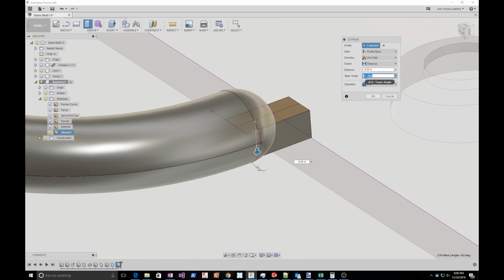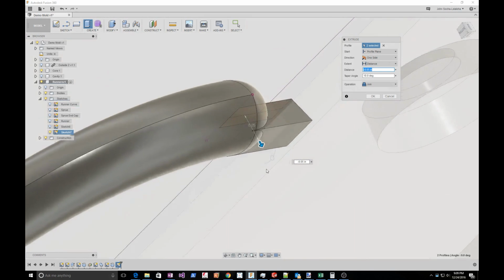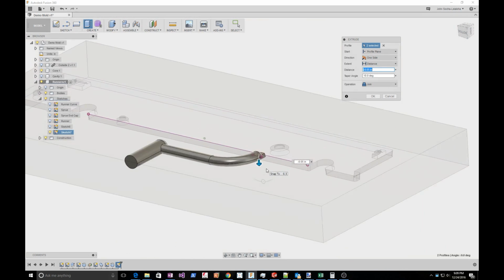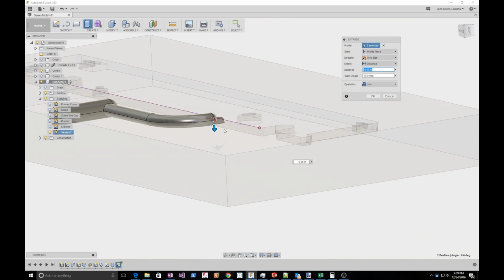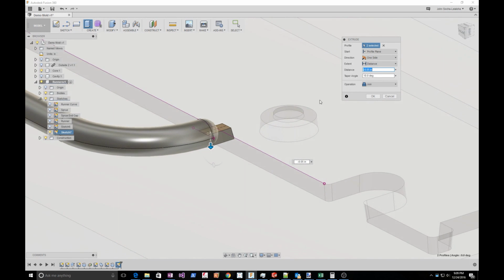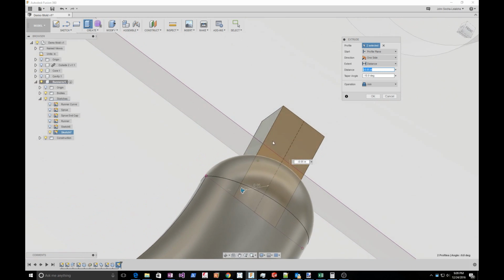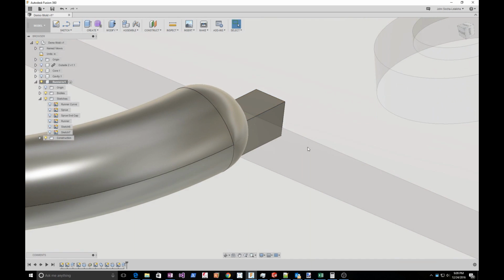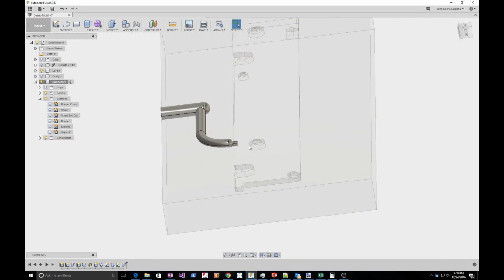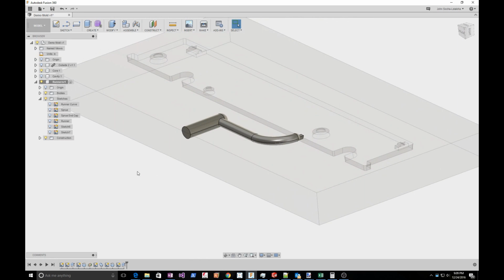Then I'm going to set the taper angle. So let me give it an angle of 10 degrees. Now that's going the wrong direction, because the top of the mold is here, and this is going to end up being an undercut. So we need to make it minus 10 degrees. And now it's going to make it easier to pull this away from the mold. Okay, so that's extending it apart, but that's okay, because what we're going to end up doing is subtracting this